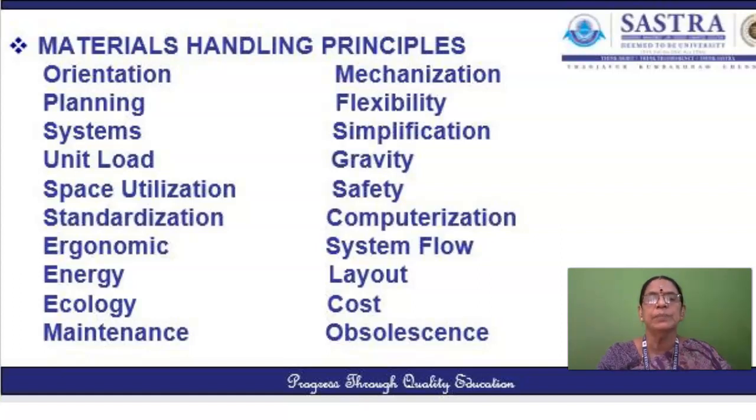Next is the safety principle. This principle deals with the safe handling of the methods and the equipment. The provision for safe handling equipments according to the statutory rules and regulations should be encouraged. So fencing should be made for the mobile machines and the pedestrian walk should be restricted in those places. The gravity principle and this principle work in combination. That is, when we are using the gravity force, the safety should be ensured. So the safety principle and gravity principle must go hand in hand.